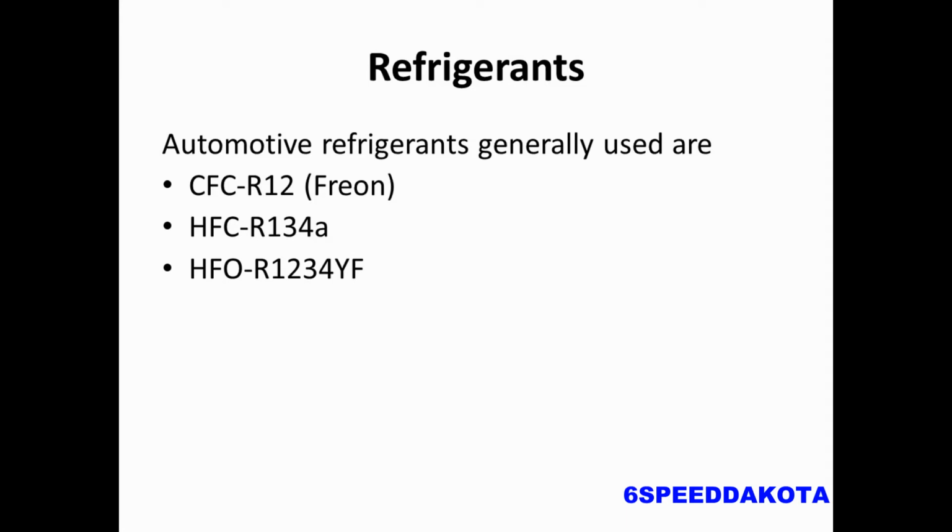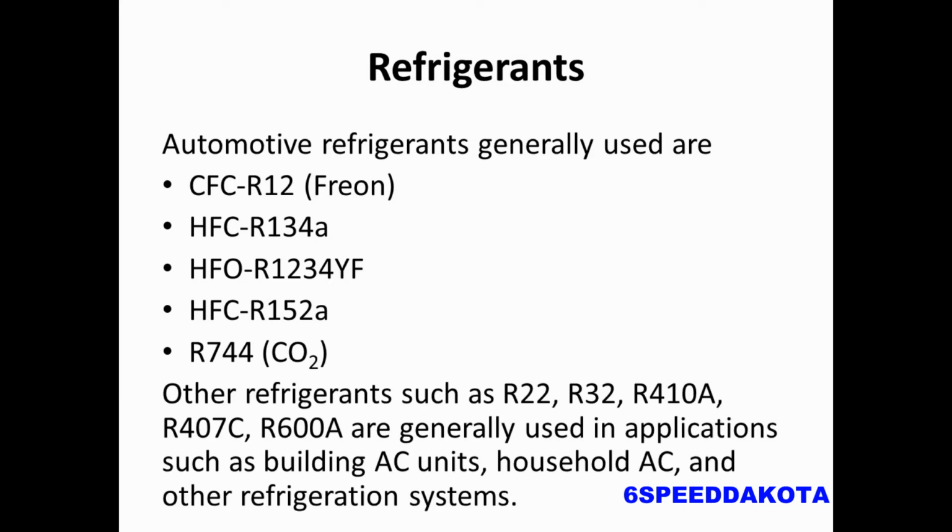We have HFO R1234YF. That's a bit of a mouthful. This one has come into play a little bit more recently, as has HFC R152A and R744, which is basically pure CO2. So we have other refrigerants such as R22, R32, R410A, R407C, and R600A, just to name a few. Those are not generally used in automotive applications, but in building AC and household AC units, other refrigeration systems like refrigerated trailers, stuff like that.